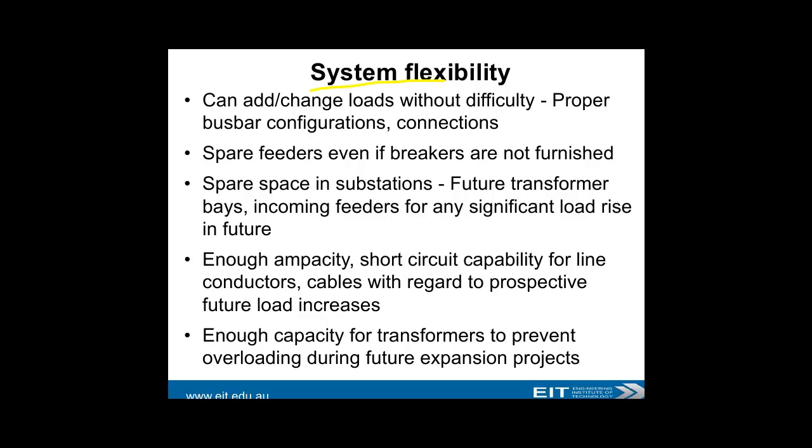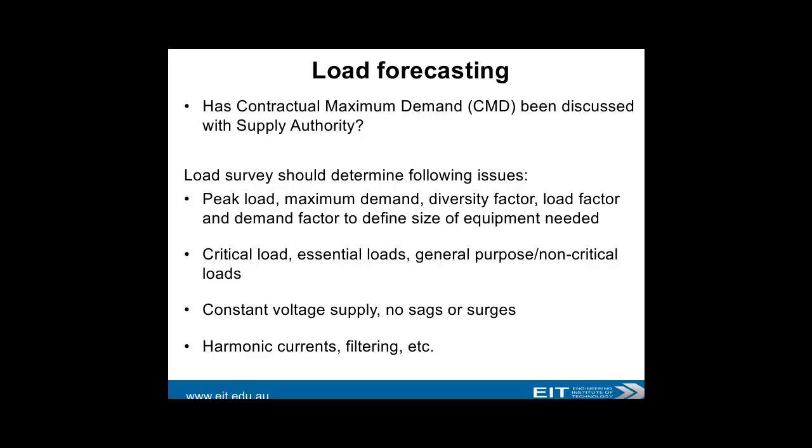System flexibility, nothing's more frustrating when you've got a power system and you can't flex it to a new requirement without shutting the whole system down or having to do extensive work. So try and anticipate growth, space in your substations, and space doesn't necessarily mean only physical space, but obviously additional batteries, and obviously area in which to put in extra buses. Enough ampacity, short circuit capability for line conductors, and capacity for transformers to include any possibility, hint of a possible overload.